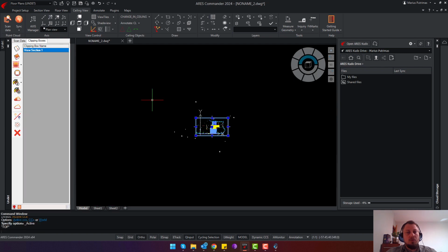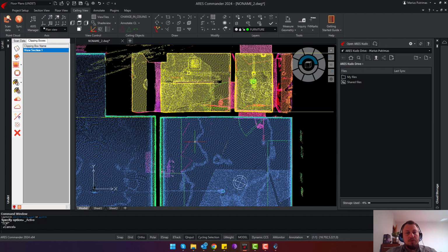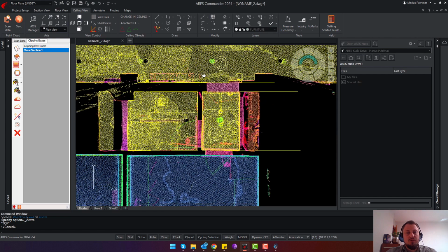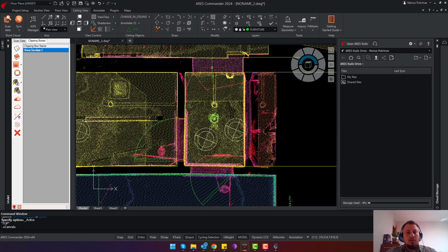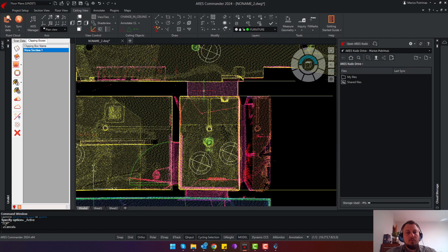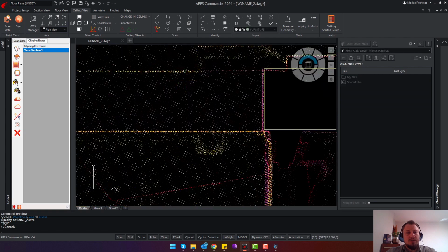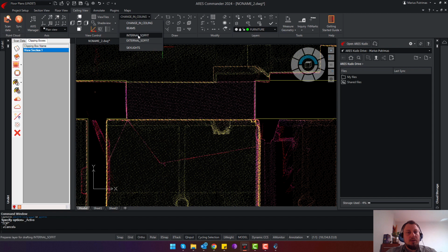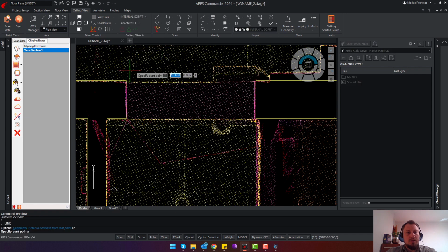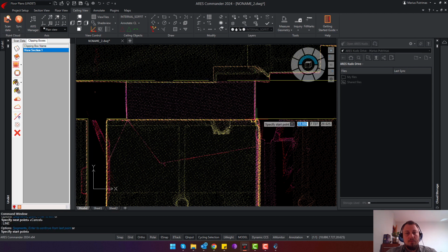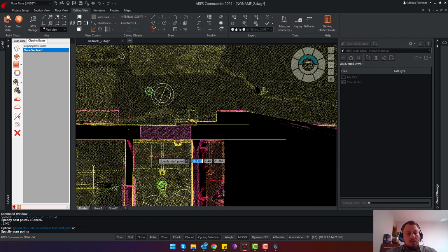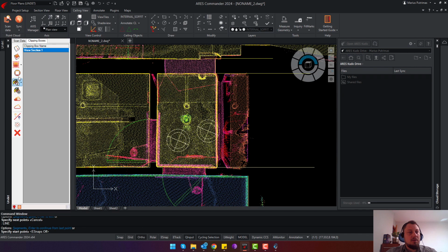And now we'll go to the top view, and I will see objects which are visible from the section lines to the ceiling. So there is an internal soffit, so I will select internal soffit, line command, F3, the snapping to the endpoints, and see that the soffit is vectorized.